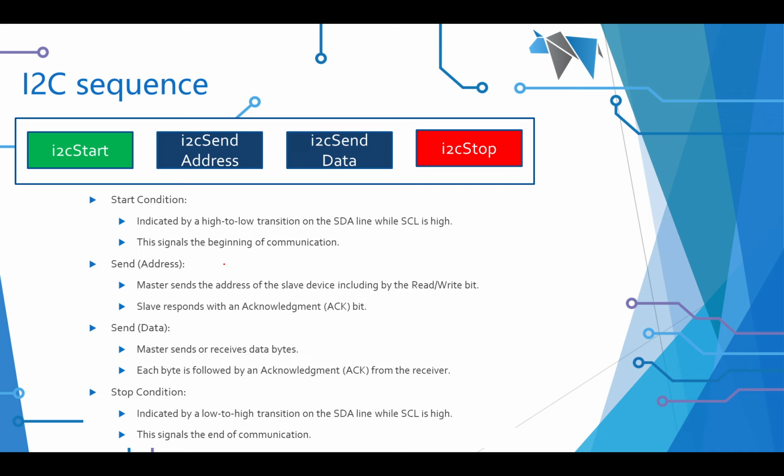And then when you send data, every time you send data, you should get an acknowledgement back, because that means that your slave device on the bus, in my case a GLCD, is actually happy with the data coming in. And if you get an acknowledgement, good. If you don't get one, then you've obviously got a problem, and you can deal with that. Then you can send data, and the same thing happens. You send the data out. As you clock the data out, you get the acknowledge back. And if you don't get an acknowledge back, you know there's a problem.